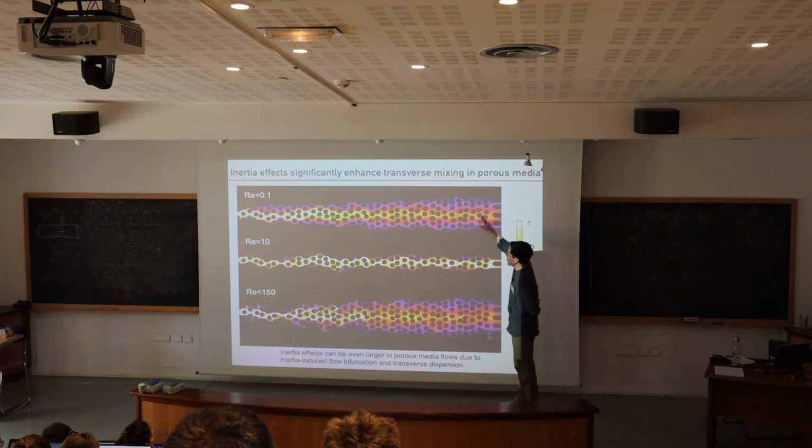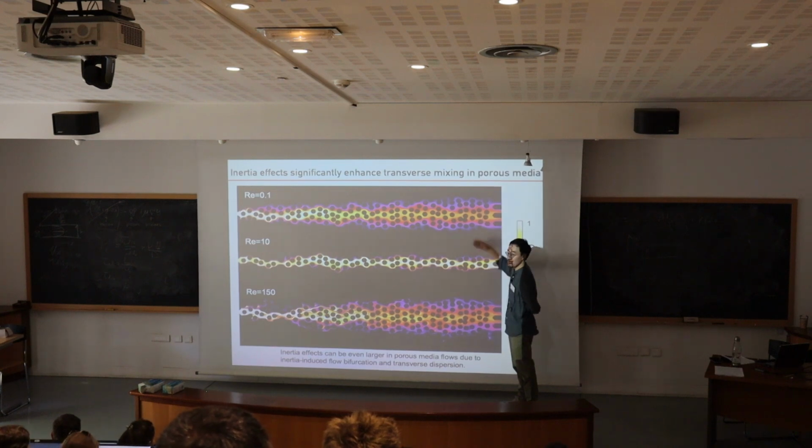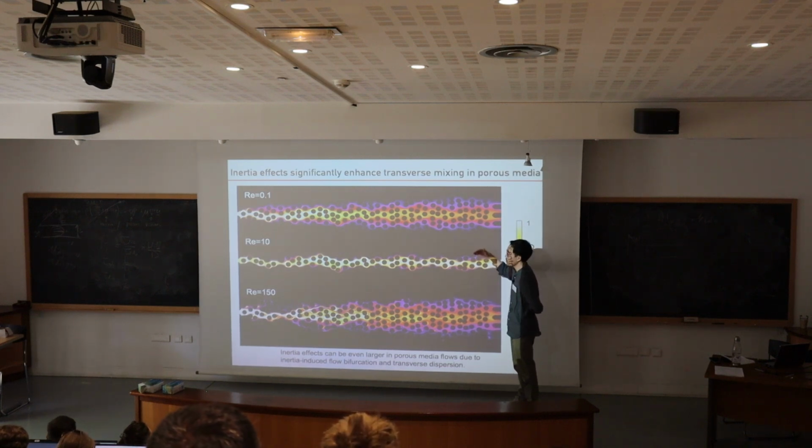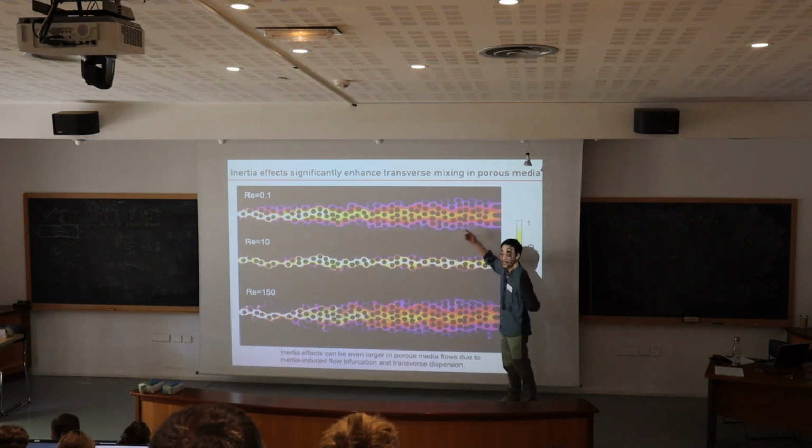So this is three different Reynolds numbers, right? And can anyone explain why we go from this to here? What is causing this? So for your information, the flow field is not changing. We still have the creeping flow. It is more or less creeping flow, close to creeping flow. There's no strong three-dimensional flow, but why do we see much more diffusive here and much more advective here? That's the answer, which is the Peclet number is increasing.